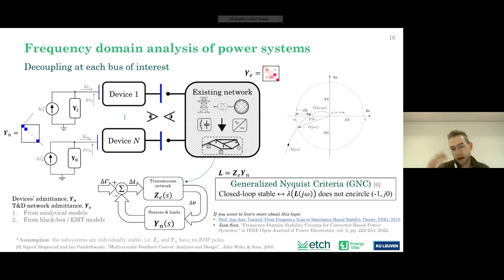They are DQ symmetric in the higher frequencies, but they are DQ asymmetric at low frequencies. So it depends in which frame you evaluate those DQ admittances. So we are doing this by basically transferring all those admittances into a global reference frame, and for that we choose the global reference frame aligned with the real axis. So basically we take the slack bus angle, which is 0. And then we express everything in this global reference frame, which then makes it possible to do stability analysis.